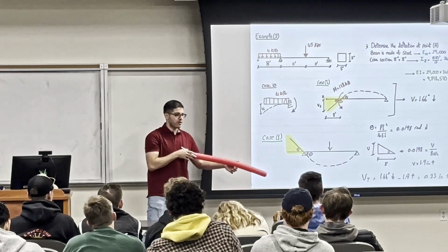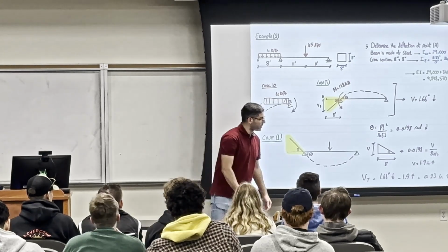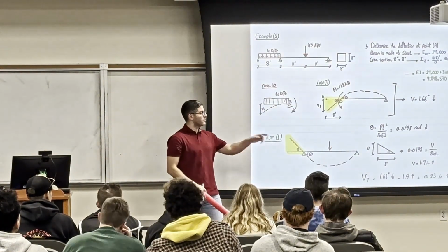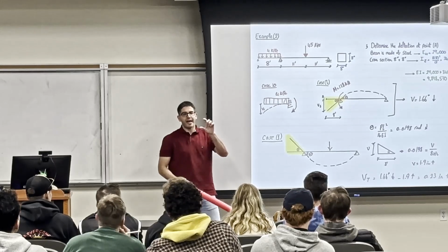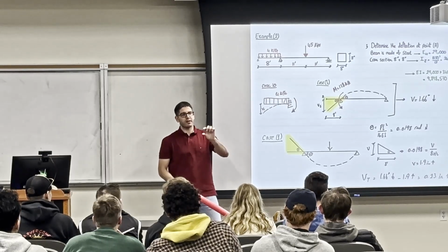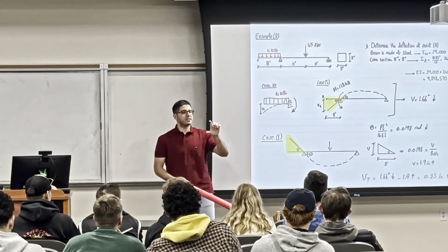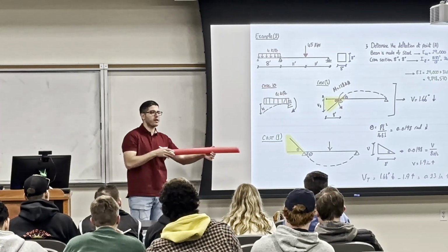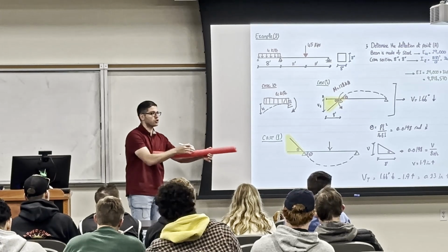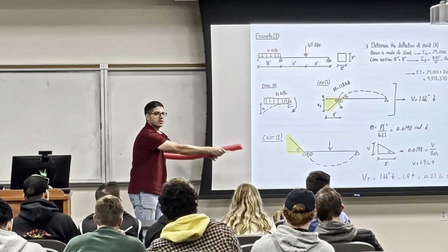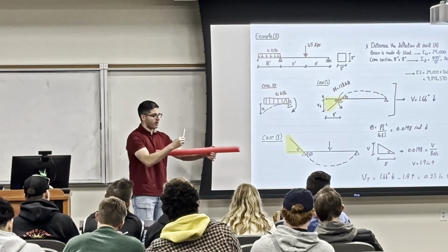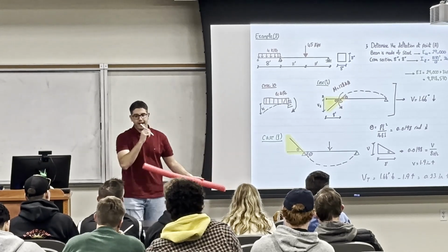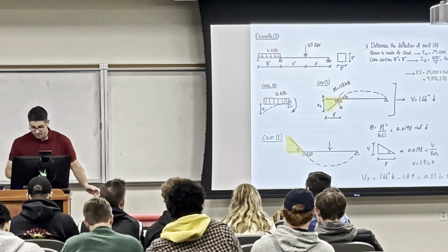For example, people who went into construction know that if this is concrete, before you put the last layer, which is the flooring, there is sand, there is a lot of material. So you might consider adding more material to make this heavier so that you might reduce the deflection at the end. Because if you added load here, what's happening at deflection? And this is also popular.